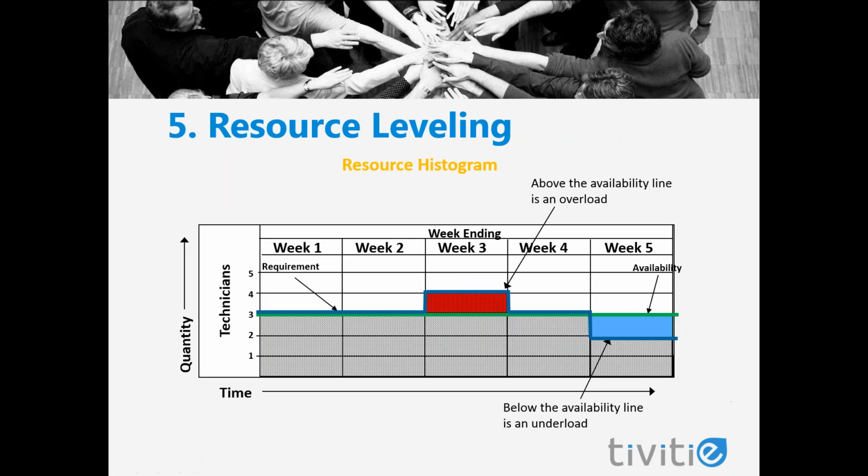If we have overallocations, or also sometimes called overloads, we can try to eliminate or at least minimize them by using resource leveling. Resource leveling is when tasks are rescheduled based on resource constraints as well as links. So Project will look at the resource availabilities versus the requirements and move things around. Leveling will eliminate or minimize the overallocations dependent upon the parameters that you specify, and we will be going over those. Ideally, what will happen is the tasks with the most total slack will be the ones that are moved because those are the ones that can afford to be moved.